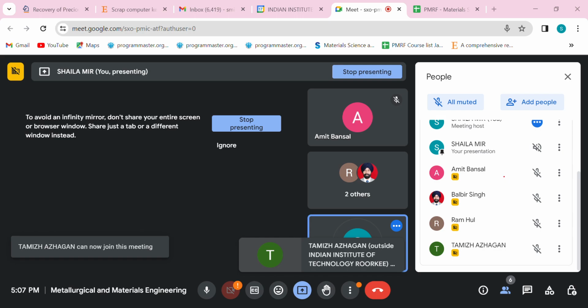So if you say they have the same material indenter, that is wrong, because here you have a diamond pyramid used and here you have steel balls being used. So the similarity cannot be based on the indenter material. Then it says the applied load is the same. Also, the load will not be the same in Brinell and Vickers. So this is also not true.